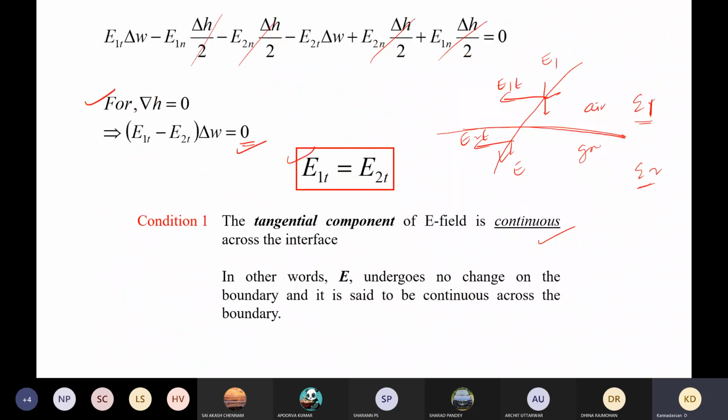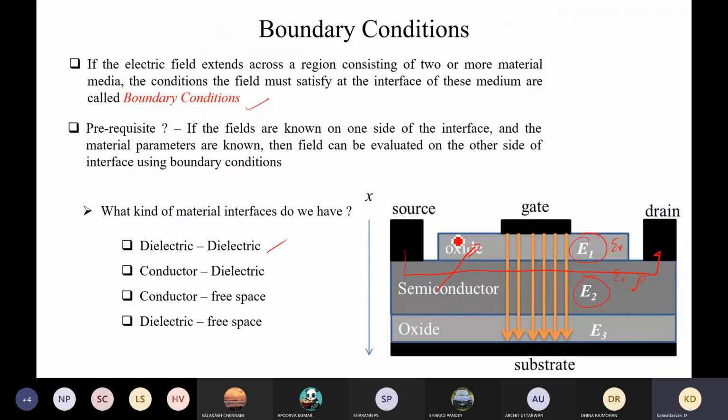So this was recently applied in some of the transistors. They have put multiple sandwiches of material. Therefore, the effective dielectric constant is reaching approximately 800. If you put a normal material, it is going to show 4, which is silicon dioxide. But due to this property, we get about 800, which means that it is about 200 times higher. And I think everyone knows that the current is directly proportional to the dielectric constant of this oxide material. So by the way, the current will increase by several times, at least 100 times in reality. So this is one of the recent works going on in nanoelectronics to increase the current of a particular device.